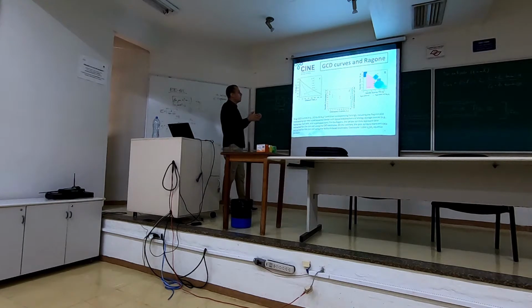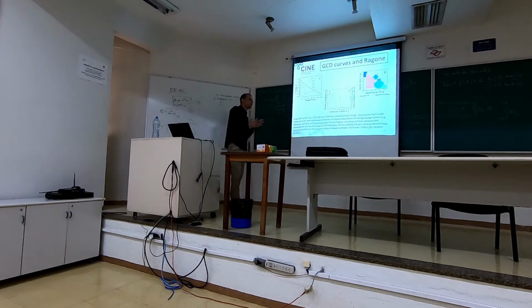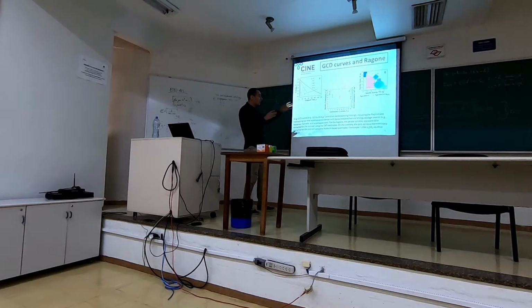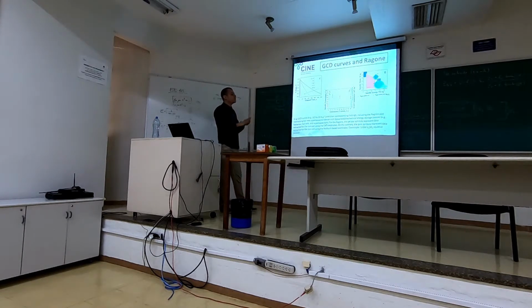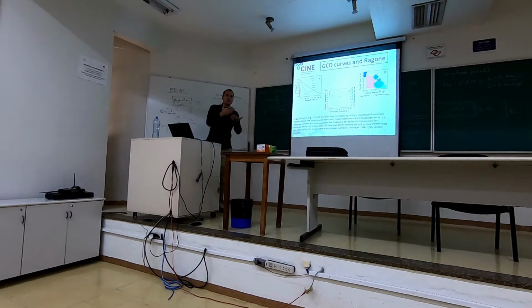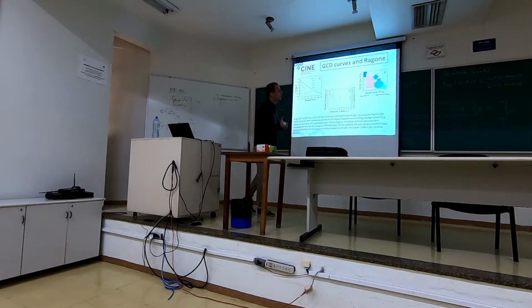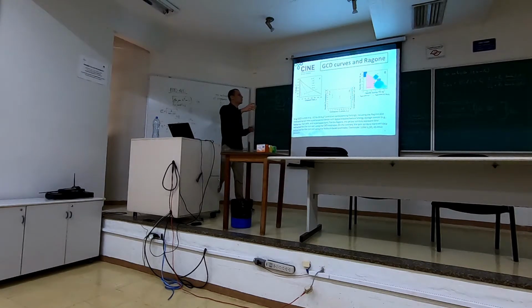And in figure F, we can see specific capacitance and area capacitance as a function of gravimetric current. And lastly, on the right side, we have the Ragone plot. The Ragone plot contrasts different electrochemical energy storage devices, like capacitors, batteries, lithium-ion capacitors, and so on.